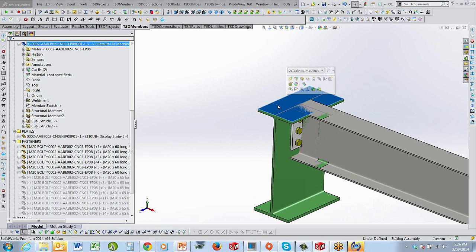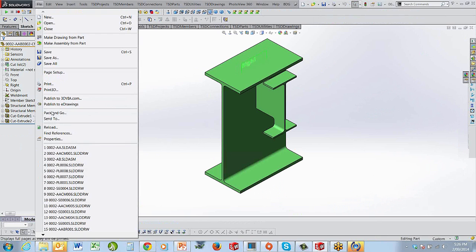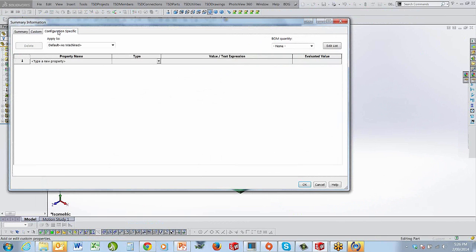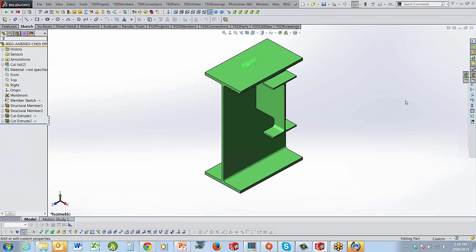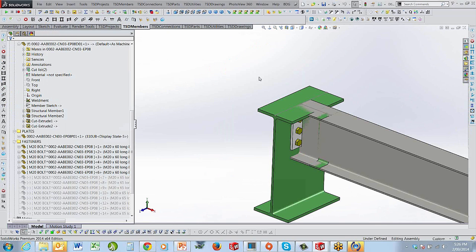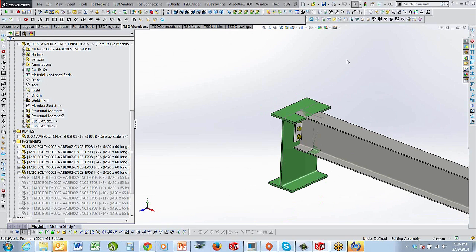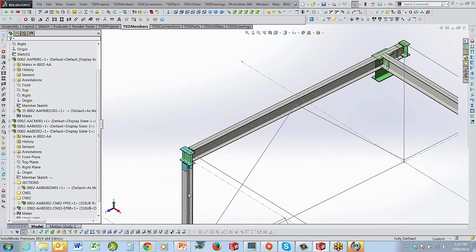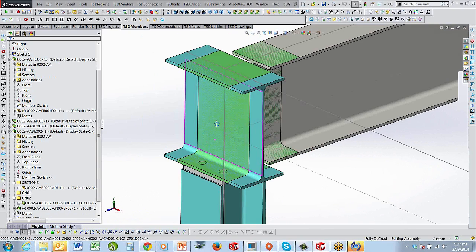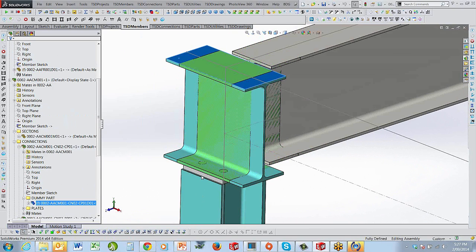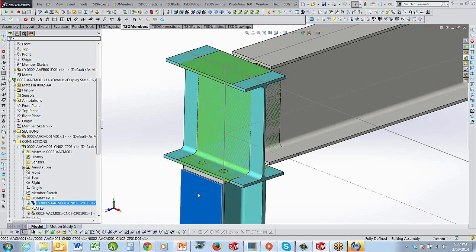Now, that's a dummy component. The dummy component contains, or it shouldn't contain, any information whatsoever inside of it. So its custom properties and its data is dead. There's nothing there, primarily because the only functionality that this thing does is just for space, just to spread things out. We'll have a look at a couple of these dummy components, as you can see. There's a dummy component here that's used for a beam that's pushing the cat plate down on that column. Let's have a look at the column. So open the column up.